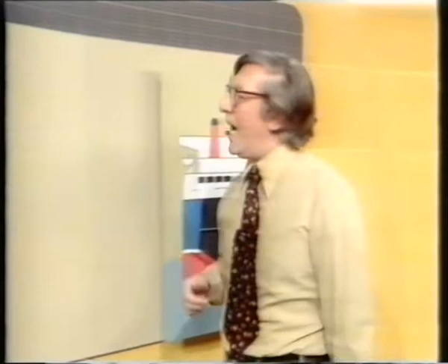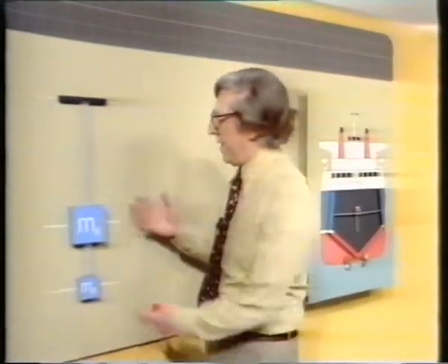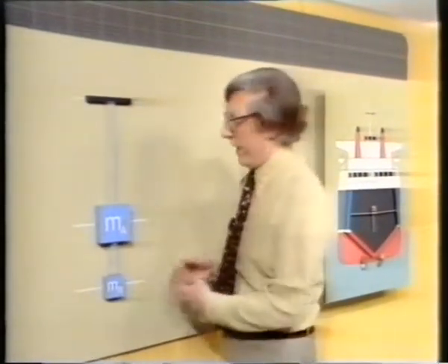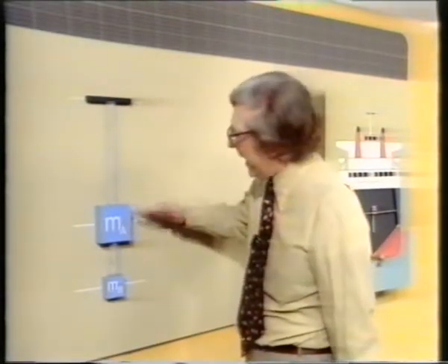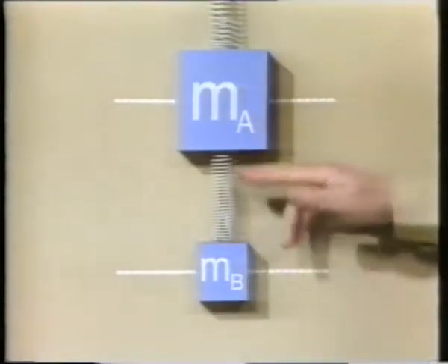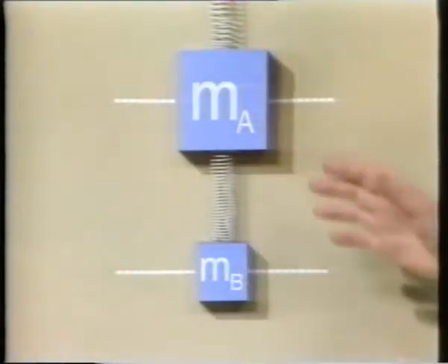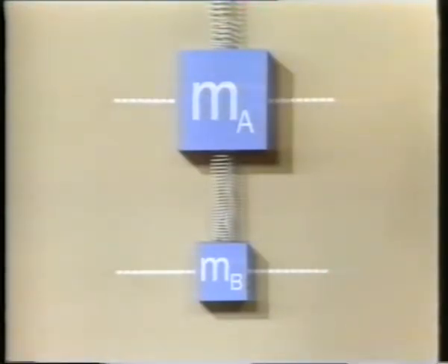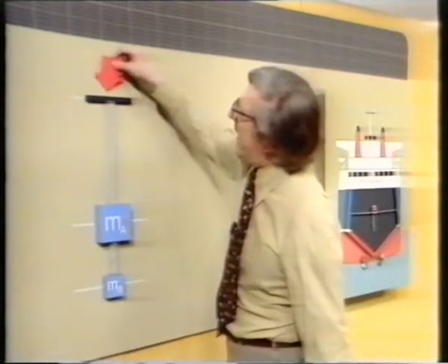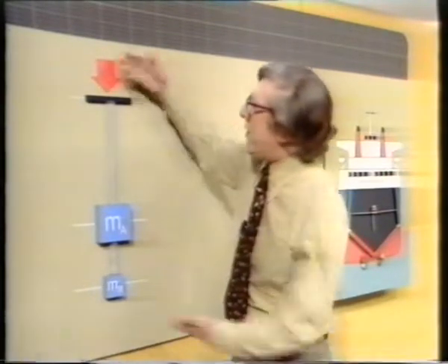Now, we can actually capture the essential ingredients by this system of two springs. The mass spring system here represents the springy car deck, and the second mass spring system here represents that contraption of the mass of water bouncing on the spring of air. Now, what about the motion of the propellers? Well, I'll represent that by a forcing function. That's that red arrow. Well, that's what it looks like mathematically.